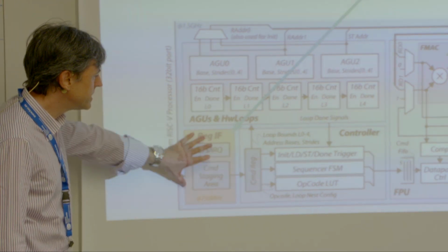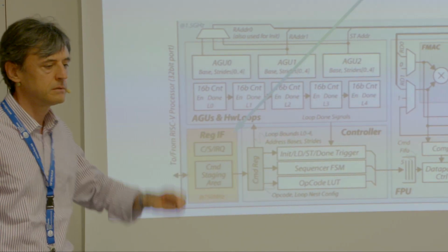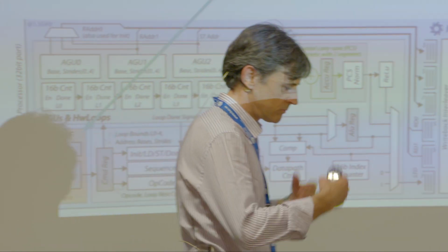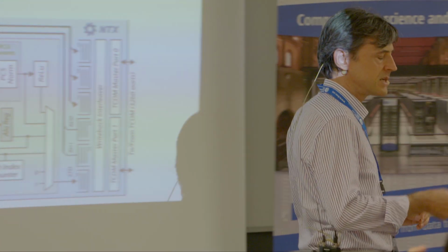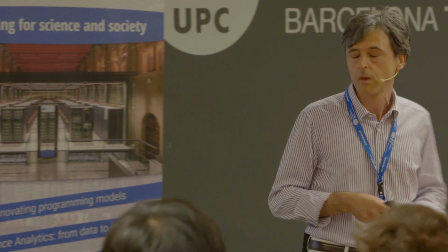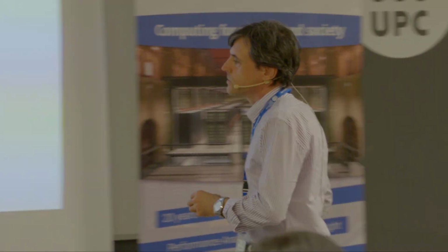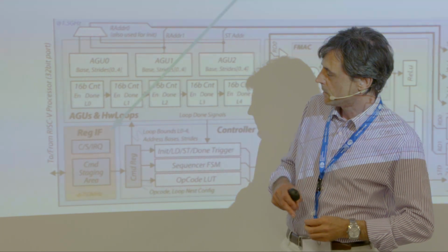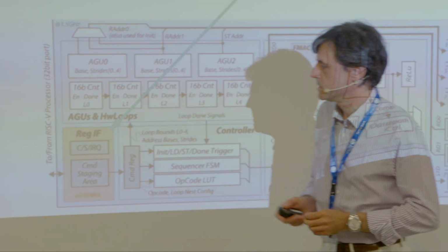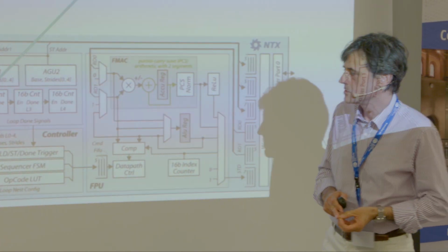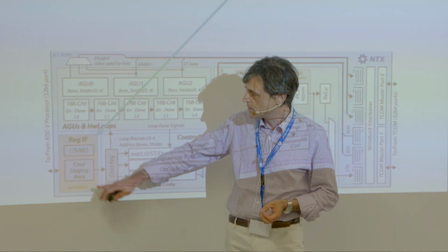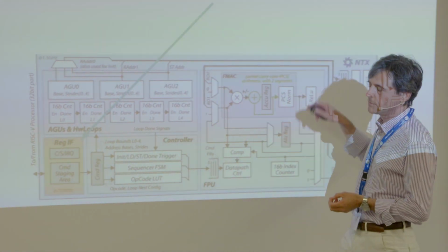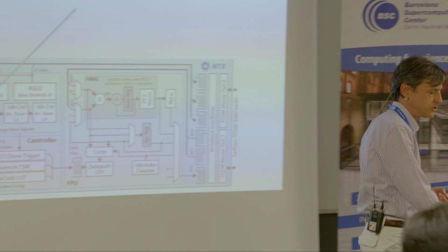And these commands are written as memory mapped commands from the RISC-V, the external RISC-V processor. So basically, the RISC-V processor writes, as if it was executing store operations into the memory, specialized control words that are controlling the operations of the microarchitecture. This is the general scheme.